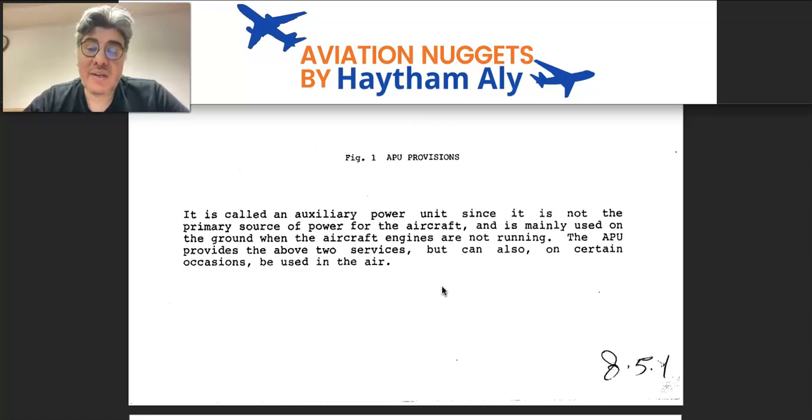What if all engines fail? There will be no integrated drive generators, or main generators, for the airliner. In that case, the APU generator may be used as an electrical power supply source in flight to supply the aircraft electrical network.